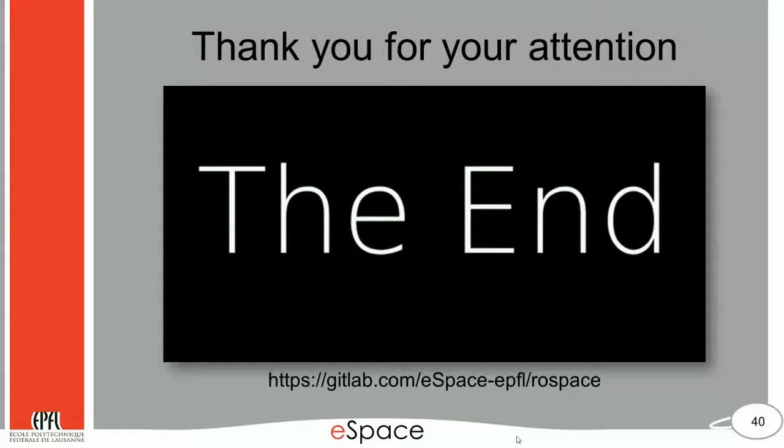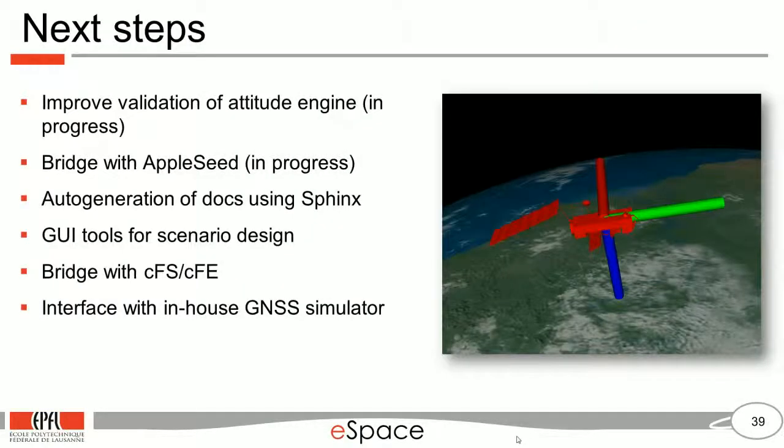Okay. Just a comment: with Appleseed, or any of those renderers, a lot of what you will see will depend upon your global illumination solution, meaning how much Earth albedo you're getting, how cloudy it is, and what sort of Earth model you have. One problem we've run into with our NASA simulations using various visualizations is double precision, because typically we like things driven in orbit, and most of the renderers don't have double precision.